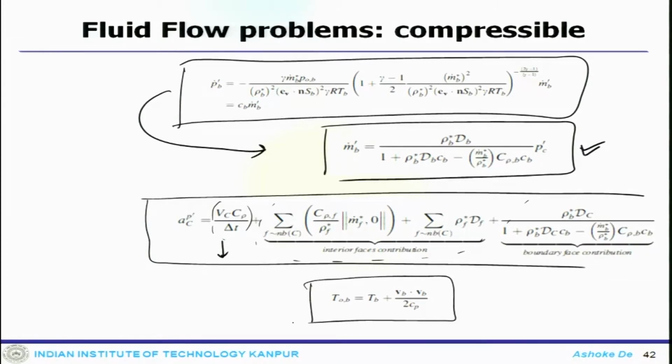So, in a compressible case, your pressure, density, temperature are linked, and whenever you do conditions with the pressure, you need to take care of the density and temperature at the same time. Now, that talks about different kinds of boundary conditions for the subsonic case.